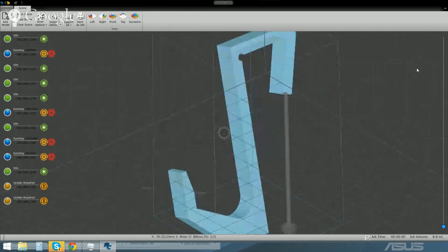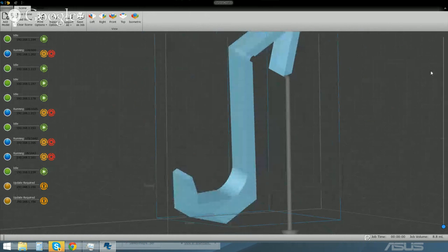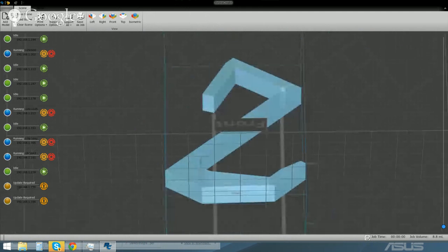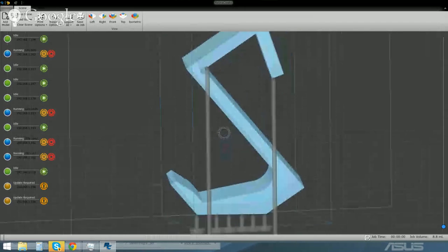And right here, this looks like it juts down a little bit, so that will need a support. And then at the bottom of this model, this whole line needs a lot of supports. So maybe one every 5 millimeters or so. These grid lines are 10 millimeters or 1 centimeter apart. So if you put one every other grid line, then that's 5 millimeters of space between them, or 2 per grid line. Sorry. That one didn't place. So now that part is supported.